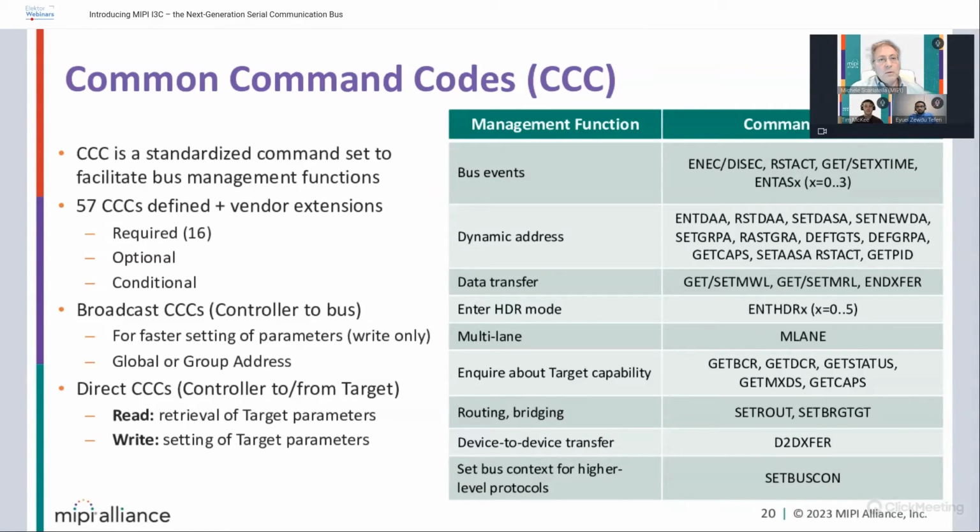There is a pattern called target reset. What should a target do when it receives this target reset? Do a full reset, or only of the peripheral, and so on. There is the delay time, and a whole number of parameters entering into some bus states, like idle mode, to save energy and so on. Quite a few command codes are actually reserved for what's called dynamic address management.